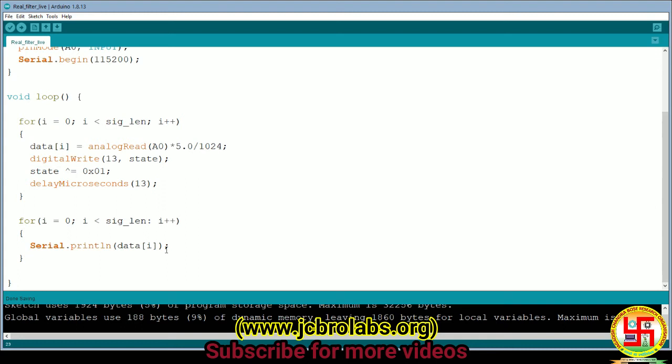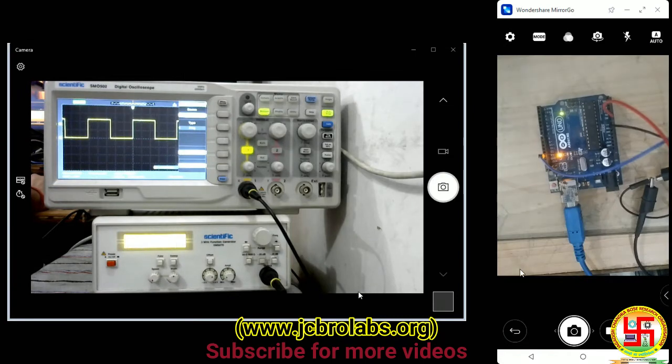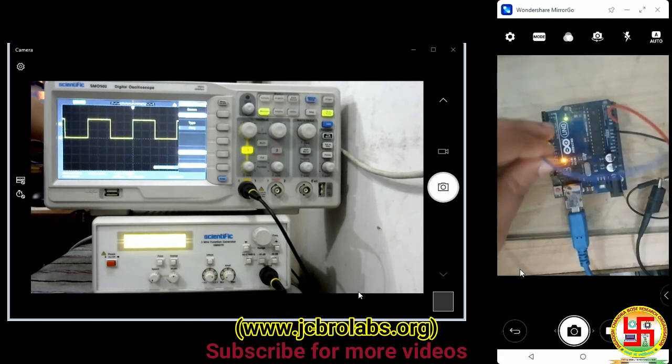Okay, so now our sampling is done, right? Our function generator to pin number 13 is done, and we know from this code we will get a sampling frequency of 8 kilohertz. So now we will connect our function generator to the DSO pin, so that we can see the waveform which we are passing to the Arduino.